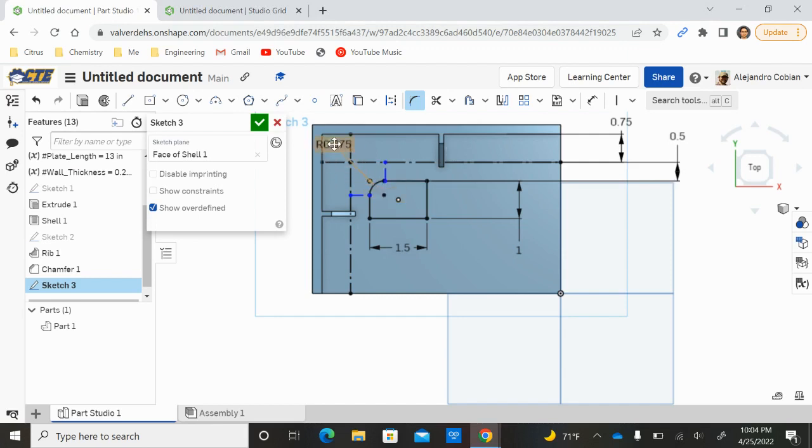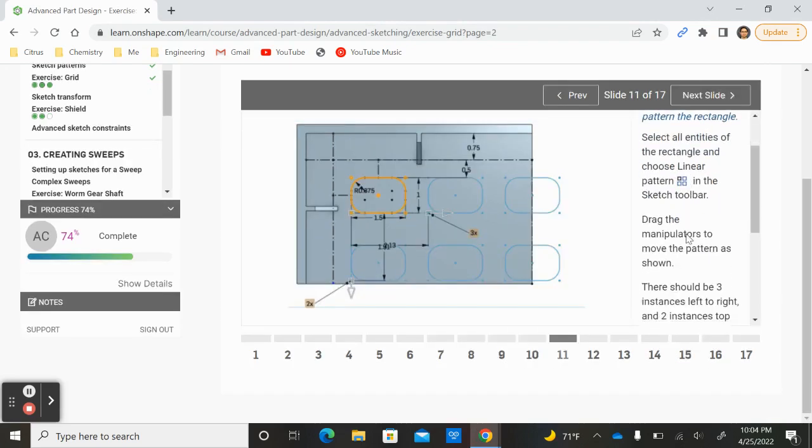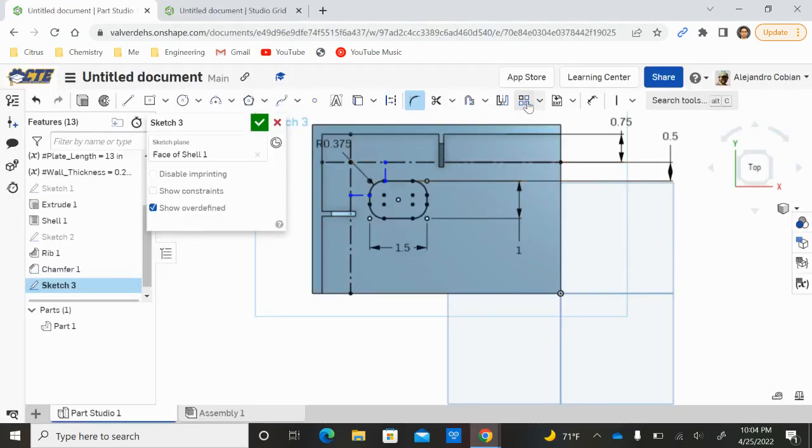We'll do the same here. Let's just drag this out. Cool thing is that the previous measurement pops up, so this will be the same length that we need. 0.375, we're good. And then finally here, 0.375, we accept that.